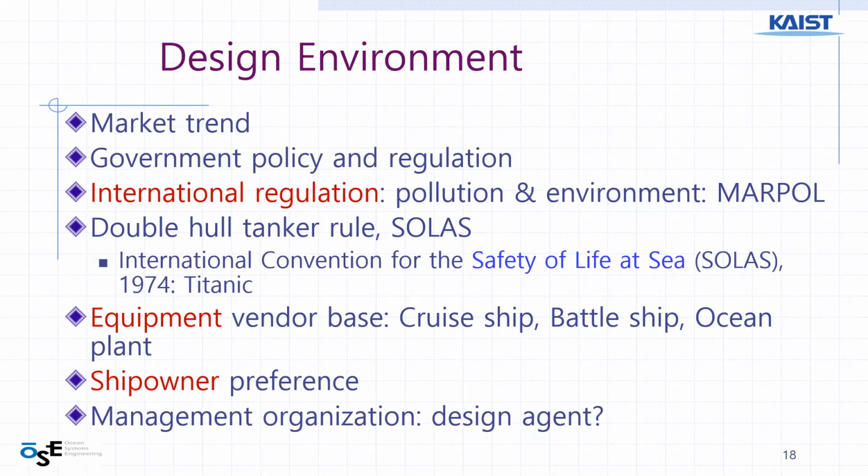So MARPOL is a marine pollution regulation. And the double hull tanker rule. The hull is the outermost skin of the ship. The internal structure is also hull, but they are saying double skin. Double hull tanker means double skin tanker. So when a ship has an accident, there can be a puncture, a hole made along the skin of the ship.